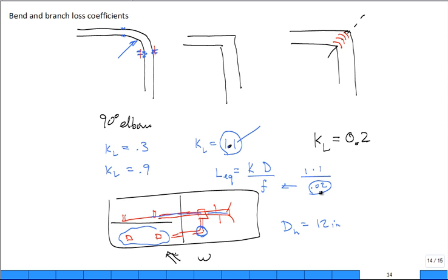So this friction factor, that's 1/50th. You come up here, 50 foot of run. It was equivalent to 50 foot of run, the resistance on that one little turn. Do you see that? I put it in perspective. No wonder you got dribble out of it.